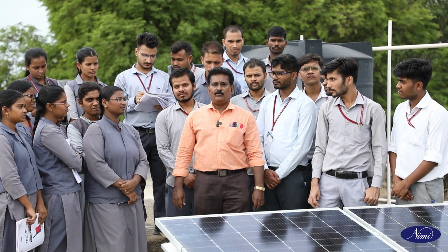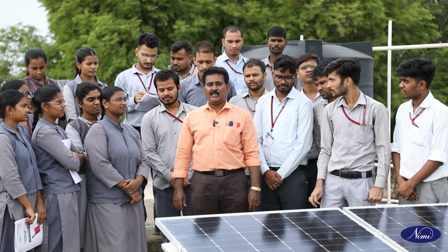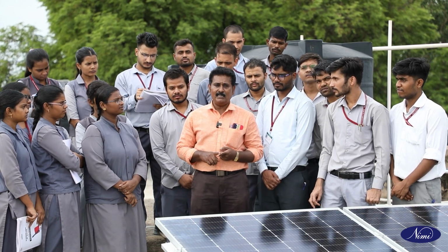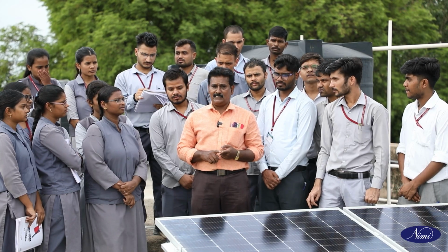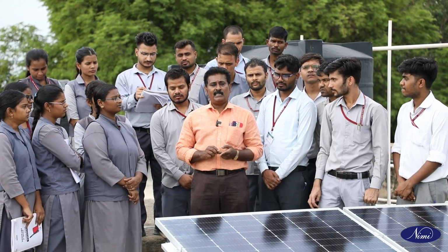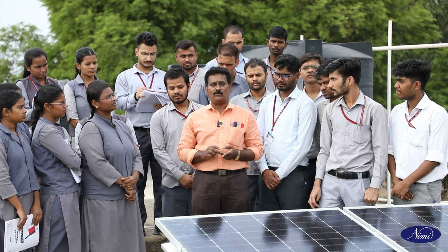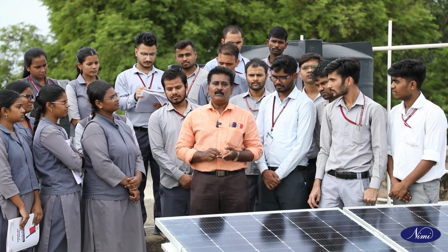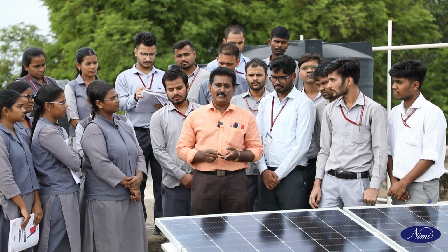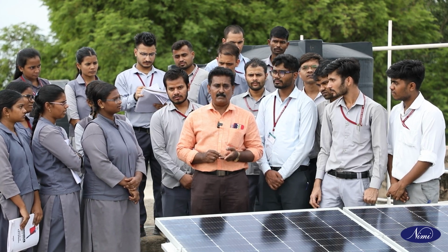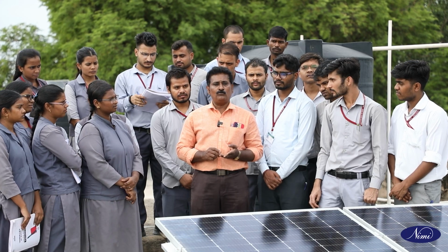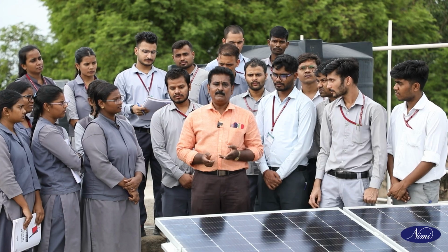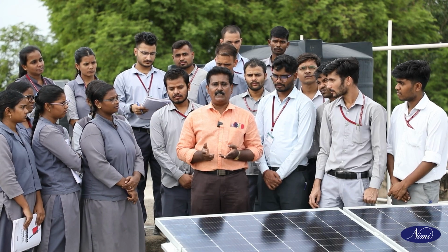Dear student, today our third day practical is over. Today we have seen 4 practicals. First one is the effect on the output of the solar panel when the inclination angle of the solar panel changes. Second one is we noted down the specifications of various solar panels and compared the specifications. Third practical is we connected two solar panels in series and measured the open circuit voltage and short circuit current. Fourth, finally, we connected the two solar panels in parallel and measured the open circuit voltage and short circuit current. Then we observed the effect of series and parallel combinations.